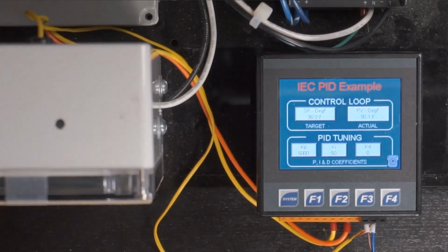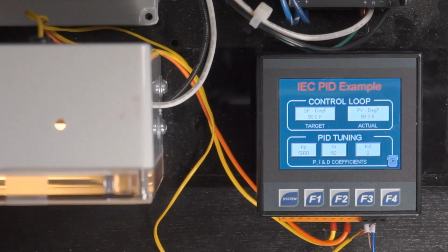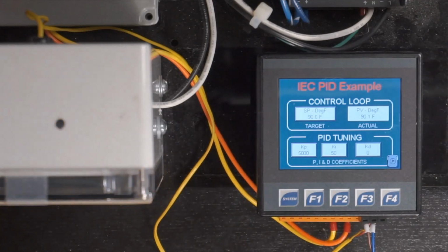So what you're seeing here on the bench is on the left, out of focus a little bit because it's actually taller than the XL4, a small plastic enclosure with a light bulb in it. And you can see that light bulb is turning on and off. And you may be saying, well, wait a minute, if we're using the heat from the light bulb to control our process and it's turning on and off, how are we using an analog output from our PID to make that happen? Well, that's where we have that separate component that's connected between the 4 to 20 milliamp loop and the light bulb to change that to a proportional on-off control. There's an extra component in there.